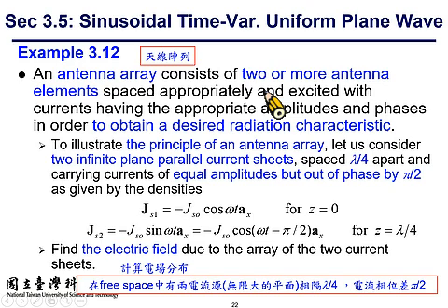Well, a quarter wavelength suggests there is a 90-degree phase difference. So for one electromagnetic wave propagating at a distance of a quarter wavelength, it shall change its phase by 90 degrees. Similarly, if the propagation distance is half a wavelength, then the phase change is 180 degrees, and if the propagation distance is 1 wavelength, then the phase variation is 360 degrees.